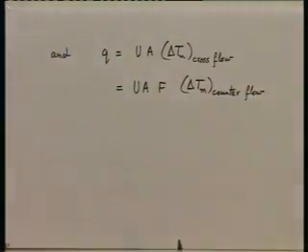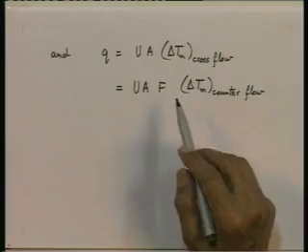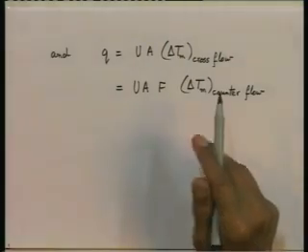So, when we have a cross flow problem, a situation of cross flow, we will calculate the delta Tm in counter flow, get f which has been obtained by numerical integration, which I will tell you shortly how we get from the various charts or graphs available, and substitute into this as our basic performance equation. Now, the quantity f, how do we get it?